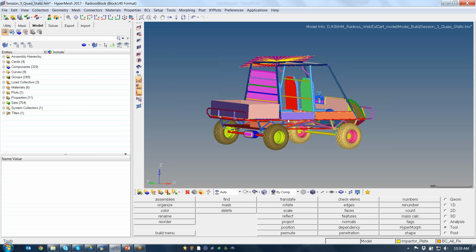Penetration is attributed to the thickness, the virtual thickness, which you don't see, but it comes from the property. Whereas the intersection is physically crossing over of elements, which you can see when you go to that region. You can physically see that elements are going inside one another, and that is not okay. So you have to make sure the models are free from intersections.